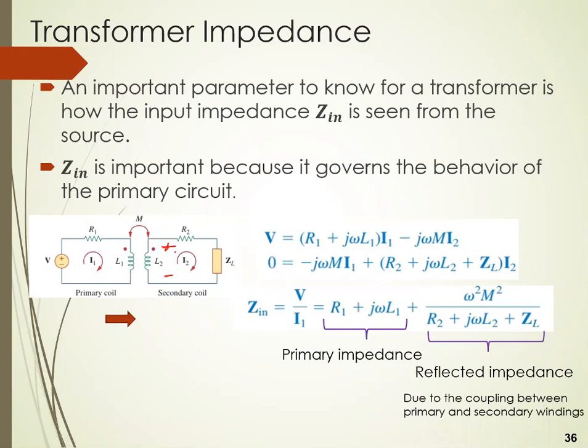So again, this voltage induced by I1 is the opposite direction of this current, so that's why you have a negative on here. In other words, if you do a KVL, this will be a negative voltage because we assume we're going in this direction for the positive, right? So that's why you get the two equations here for the primary and for the secondary.